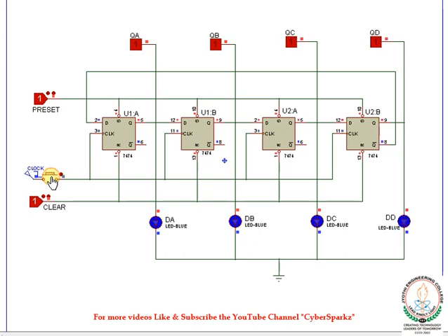On the next clock pulse, output becomes 1111. Here you can see for all these clock pulses, starting from the first flip-flop, one by one flip-flops are setting for each of the clock pulses. Now, as all the flip-flops are in the set condition, from the next clock pulse onwards, one of the flip-flops will be resetting its state for every clock pulse, starting from the first flip-flop itself.